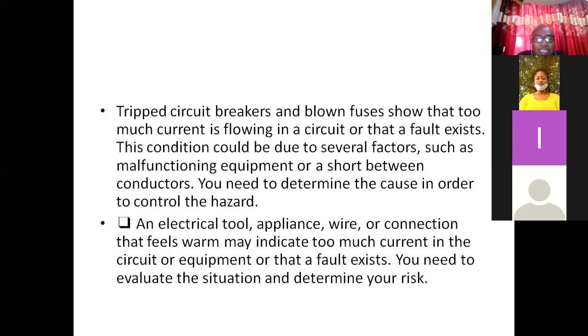It shows that there is a fault in the wire, or the wire is carrying a current that is too much for the load. Imagine you want to use an AC that is 15 amps, and the wire or the socket that you are using is 13 amps or 10 amps. It will be cutting all the time and it will be causing problems.